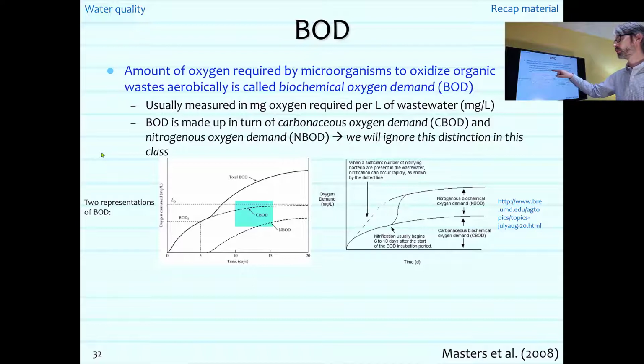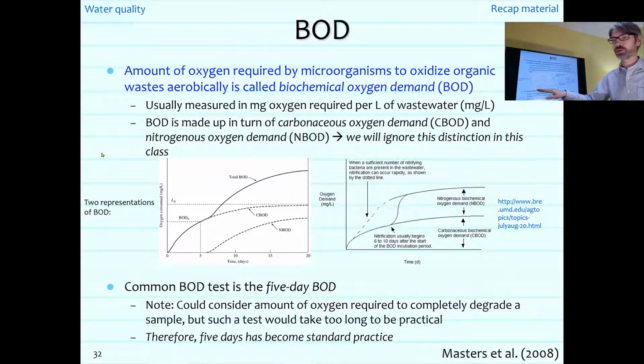BOD is made up of two parts. First of all, we have carbonaceous oxygen demand, or CBOD, and secondly, we have nitrogenous oxygen demand, or NBOD. We're going to ignore this distinction in this class, and we're going to focus on a common BOD test, which is the 5-day BOD.